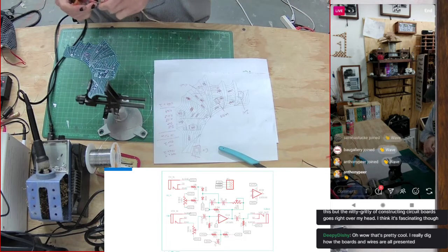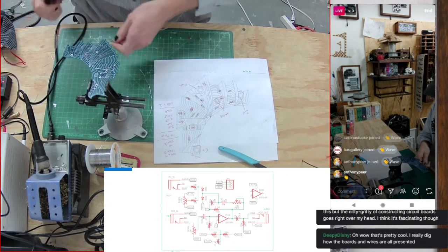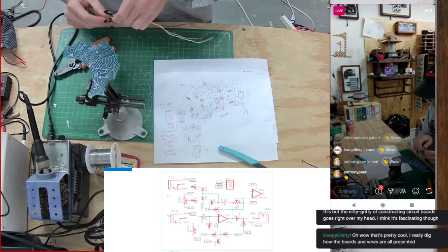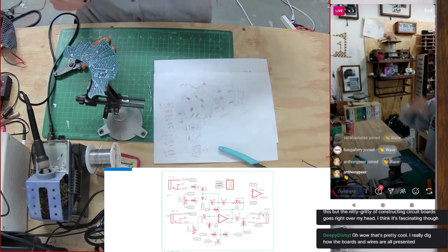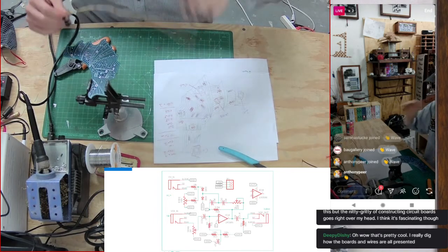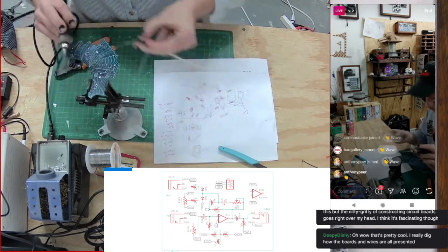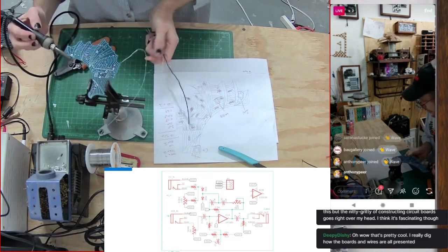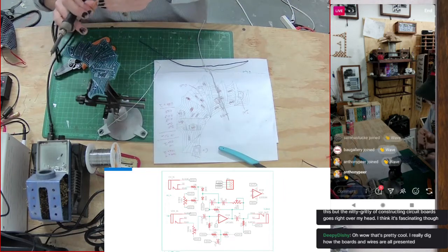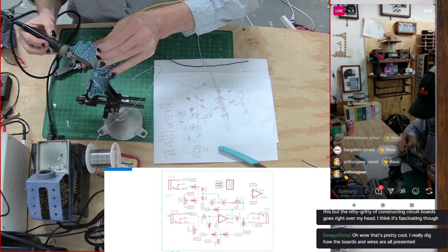In this case, these circuits actually have 3 poles: plus, minus, and ground. Ground being a sort of midpoint. And these run on what's called plus minus 12 volts, which is 12 volts above ground and 12 volts below ground, and between your 2 above and below, you have 24 volts difference in voltage. That just gives you a better range of power options and amplifications. But it means you have to have a special power supply, which I have, but that's why there's 3 wires that have to get connected for power.